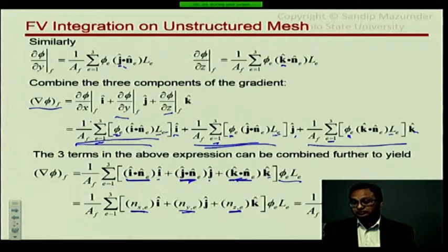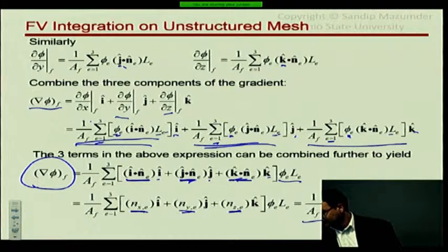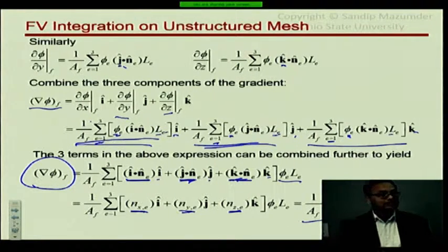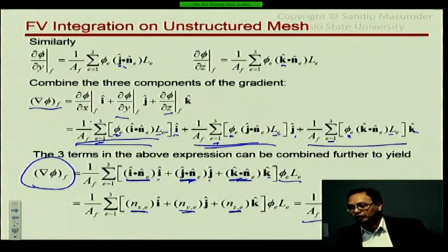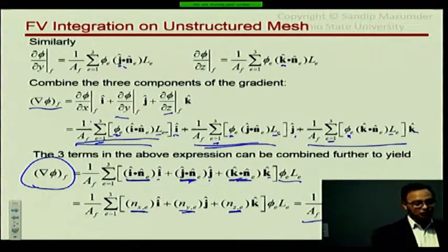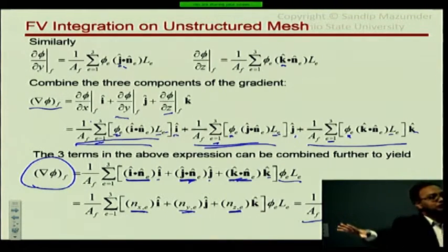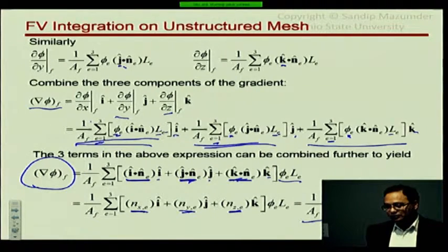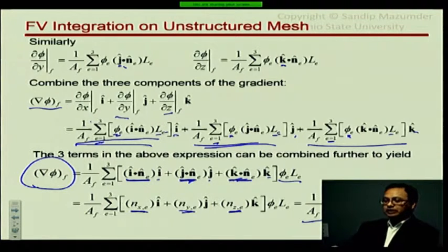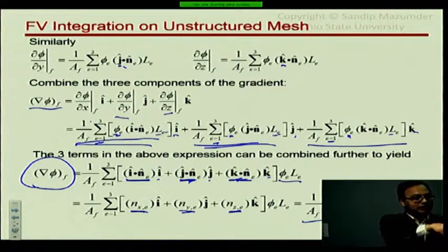Okay. So gradient of phi is this quantity, even outside of this finite volume formulation and so on. Suppose somebody gave you a problem with a distribution of phi on some arbitrary area. I take this surface and say, here are the values of phi at the different locations. I have made a mesh out of it, and I am giving you the values of phi in each location. And somebody tells you, tell me the gradient of phi at that point.